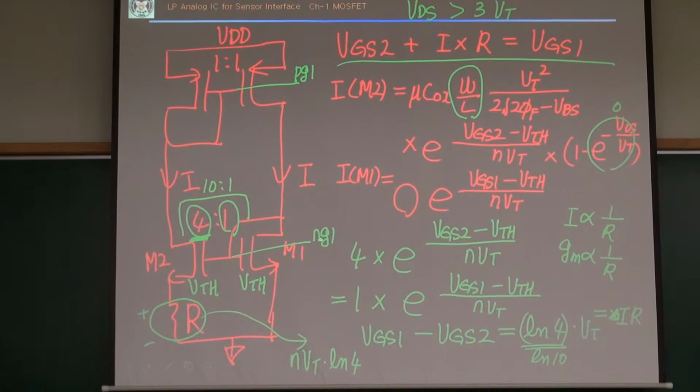So this should be connected to PMOS, because it must be connected to VDD. The source must be connected to VDD, something like that. Those PGs are for PMOS, which is a sourcing current source. This is connected to NMOS for the sinking current source. We cannot use PG1 here.